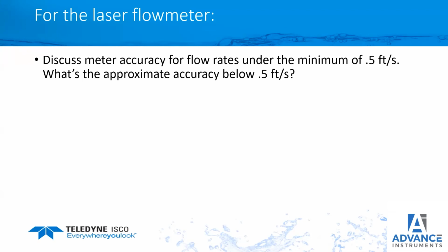As far as those readings, they look accurate. The customers I've dealt with have also thought that was an accurate reading. You'd have to do some independent testing with a bucket and stopwatch or something. If you have that slow a velocity, you probably could do that.